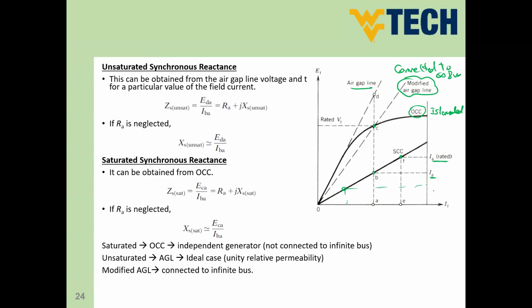What I recommend for that test, you can just take 2-3 values because of the accuracy of the measurements. So if you have 2-3 values, try to make a linear relation or interpolation between the points in order to get the straight line of the short circuit characteristic.